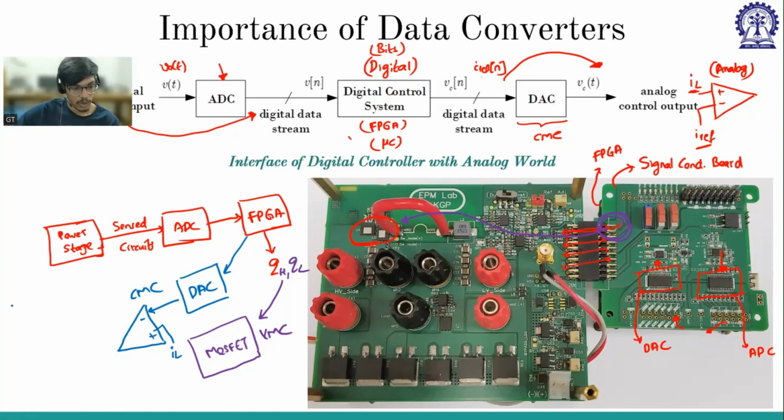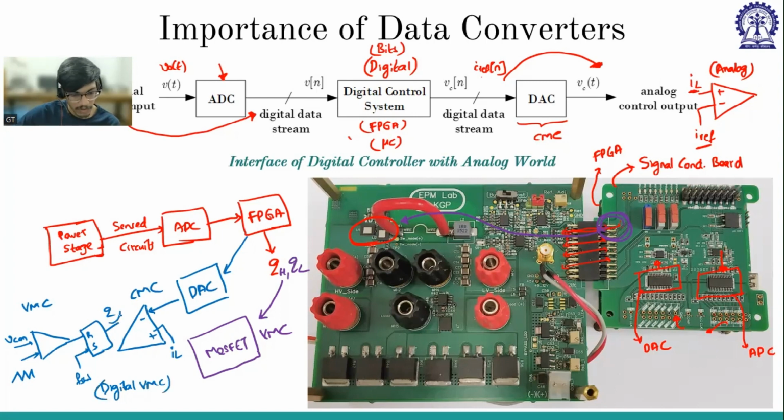Yes. So in the case of voltage mode control, if you consider the architecture, how will it be? We are comparing VCon with the ramp voltage. The output will give reset, and set is FSW. And this is the gate. So when we talk about voltage mode control, we say digital voltage mode control, because everything is digitized. So this Q is coming from the FPGA. This entire part can be implemented in the FPGA. How we can implement that will be discussed in the upcoming weeks, but just for your understanding, this entire thing can be implemented in FPGA.